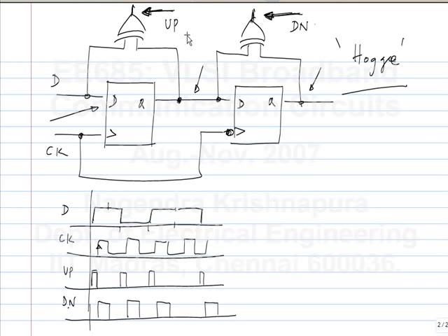Essentially it has to do with the bandwidth of the locking process of the phase lock loop. If you have very few transitions, it will take a long time to acquire lock, right? Because you get information about the phase difference here, let's say, and if your next transition comes only tomorrow, then it has to just hold that phase till tomorrow and then update the correction afterwards. That is one consequence: if you have low transition density, you will have low bandwidth. That is, it takes a long time to lock.